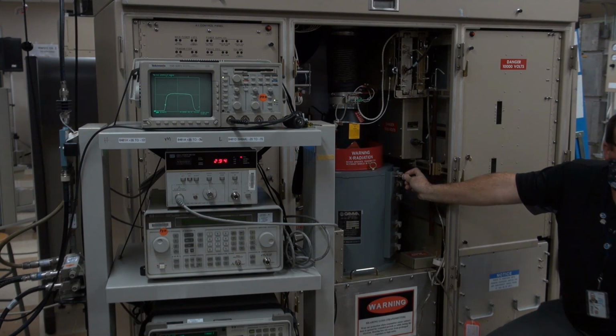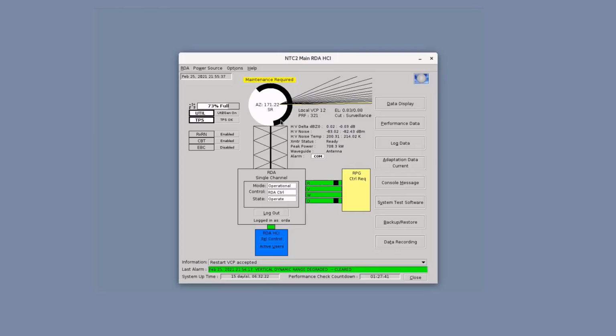The FIR filter parameters specified in this procedure are optimal for a transmitter aligned per EHB 6-511. If any part of this procedure does not fall within limits, you should verify the transmitter power and pulse shape. Perform steps 1 through 2B of Table 6-9 to place the system in standby state.